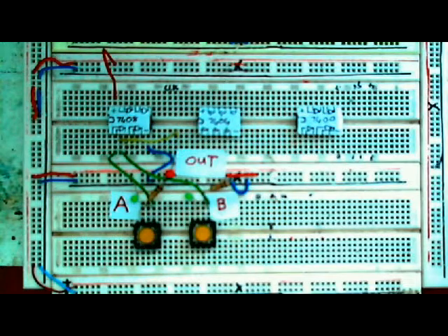It is good practice to ground the inputs of the unused gates, as they will fluctuate between a high and low state, causing unnecessary load on the IC. However, in this case, I am leaving them floating, so as not to clutter the board, so it's easier for you to see what is going on.